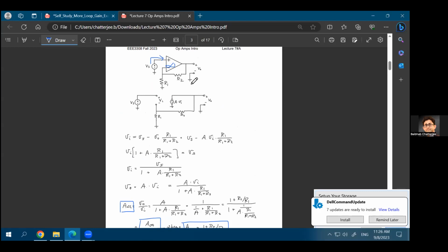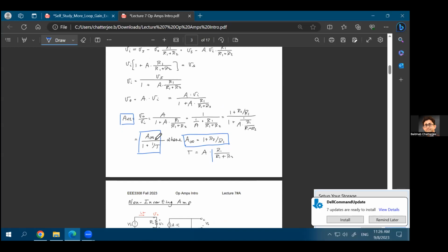Open loop gain is what we have been defining as the loop gain, that T. So A multiplied with beta is called open loop gain. A infinity divided by 1 plus 1 over T is called closed loop gain. A itself is called the feed forward gain. If that feed forward gain is infinite, then the gain of the overall system is equal to A infinity.